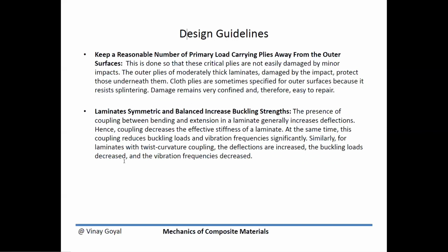Now, one of the things I want to mention there is that you can use the idea of sacrificial plies. So say you have 20 plies that you need for a composite, perhaps design to 26, and then keep the extra weight penalty mostly to protect yourself from potential impact damage. So you have to kind of balance what you want to do. If you want to keep it to 20 plies and you don't want to have any pocket margin, then perhaps you have to up your game when it comes to implementing the impact damage protection plan.